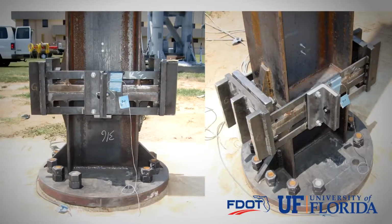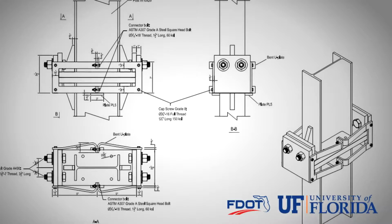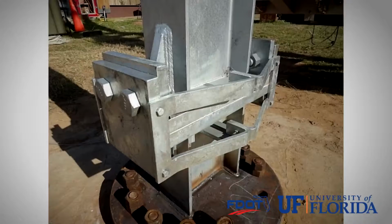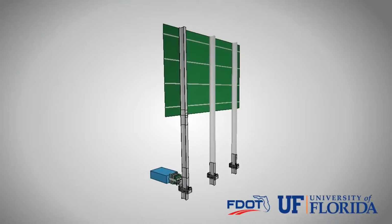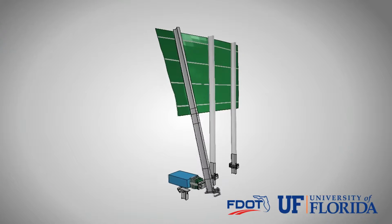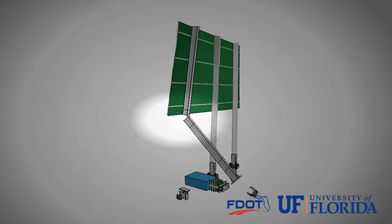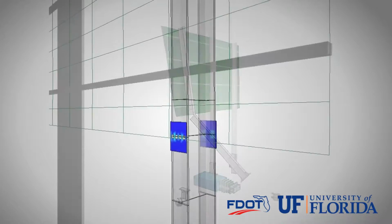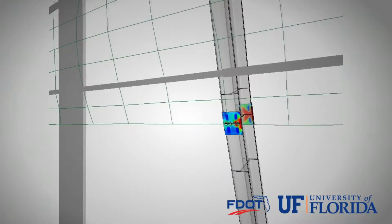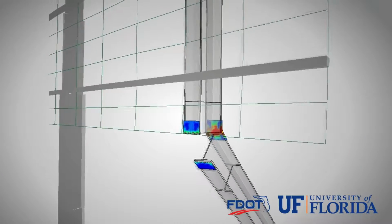Subsequently, the purpose of my thesis project is to optimize, simplify, and redesign a breakaway system for a 10-year design life due to this new policy change. Finite element analysis is a cost-effective tool that has been used to design the breakaway systems presented. Through these simulations, components such as the shear control moment collar and the fuse plate hinge plate connection have been optimized and designed. The results of the finite element numerical simulations have given insight into the proposed system behavior.